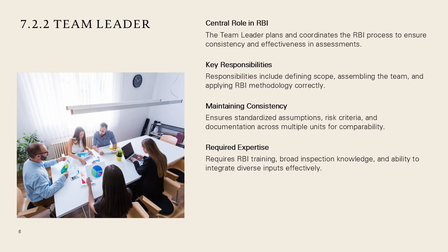API RP 580 emphasizes that the team leader should have sufficient RBI training and experience, as well as a broad understanding of inspection, corrosion, and risk concepts. While the team leader may not be the deepest technical expert in every discipline, they must be capable of integrating diverse inputs into a coherent risk picture and resolving disagreements in a structured and transparent manner.